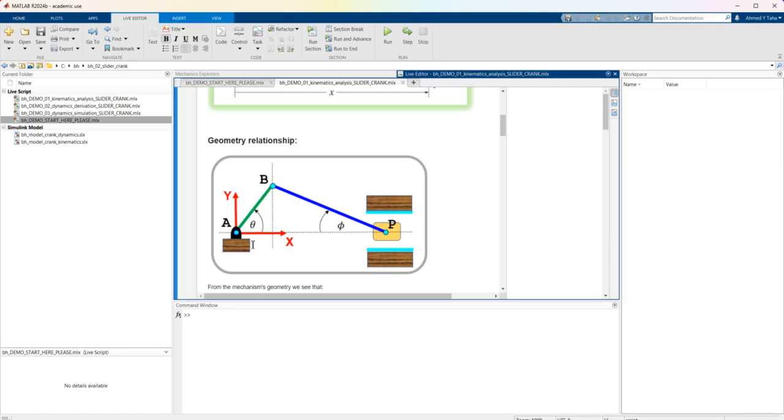I think that, as I told you once again, we had some example solving this one, because here we can find the velocity at the B, which is going to be perpendicular to the green link, by multiplying the omega by the R value, which is the link AB length. And then between the B and the P, we're going to do the relative velocity equation. Okay, we're going to say that the velocity at the P is going to be the velocity at the B plus the omega multiplied by the length BP. Okay, well, which is once again not that hard.